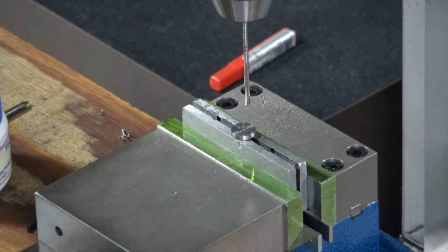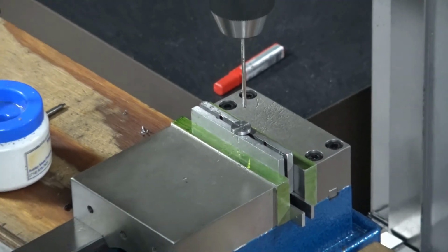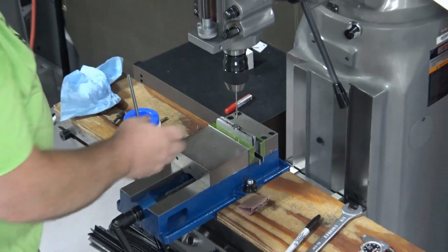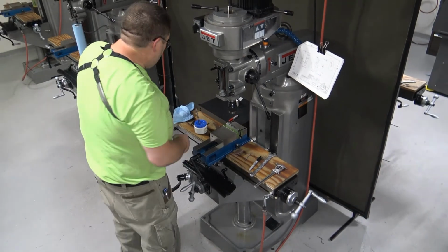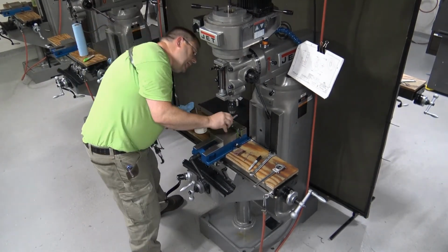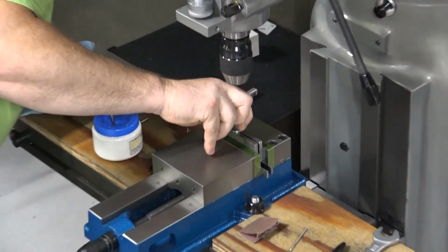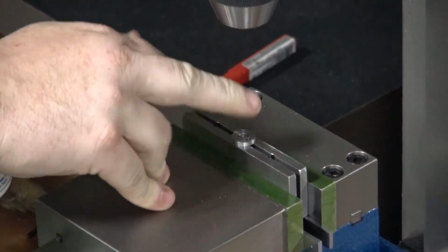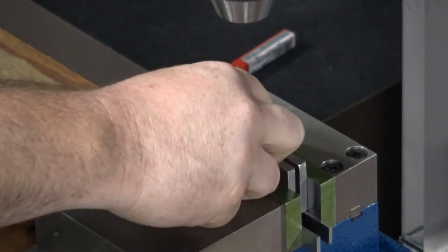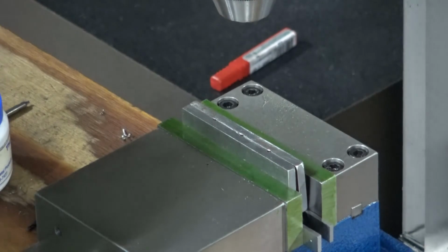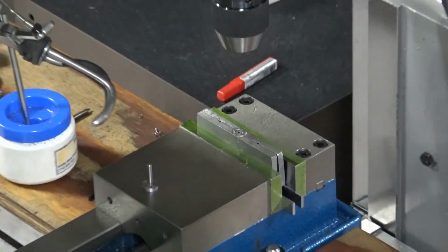If it turns out that we reamed with too large of a reamer, we're going to have to reset everything back up. Okay? So let's take our reamer back out. What I'm going to do is I'm going to countersink that hole while it's set up in the machine, because I do tend to have a little issue with holding on to things and countersinking them. Here's our back side of that crankshaft.